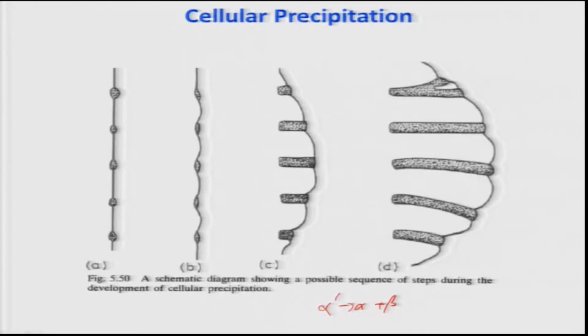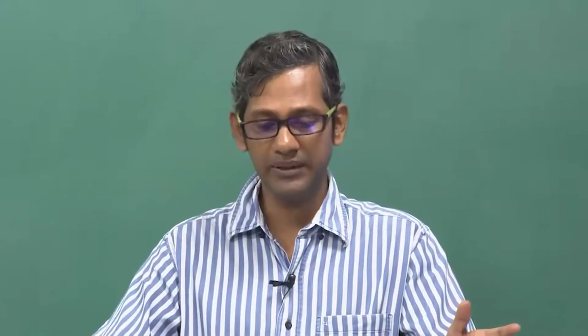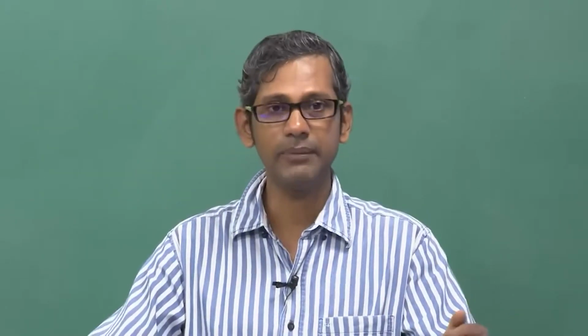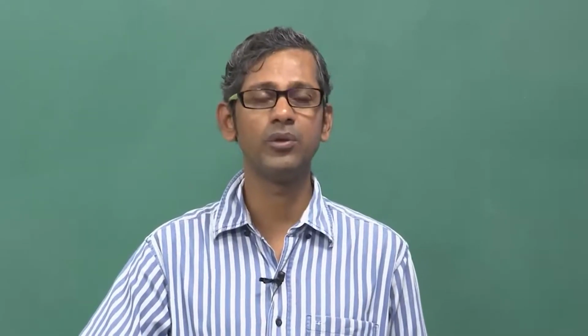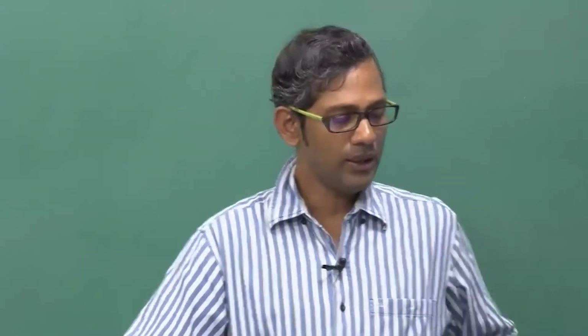Okay. So, now the question is that the mechanism by which this transformation happens is still debated, it is not yet understood. As I told you, in another maybe 10-15 minutes, whatever time I have in this lecture, I am going to show you a few microstructures and try to explain how things happen. The grain boundary mechanism by which the grain boundary nucleation develops into cellular precipitates differs from one alloy to another alloy. That is one of the problems. That is why it is not fully understood.